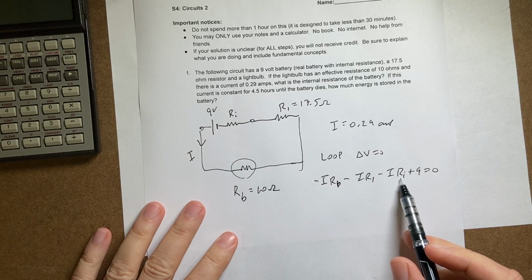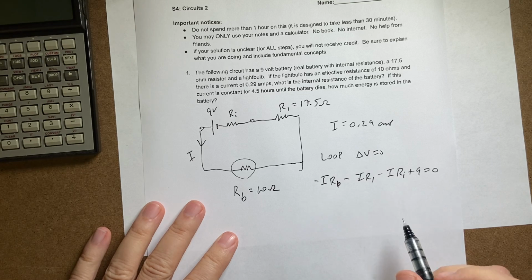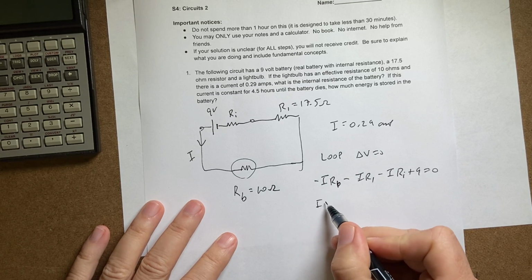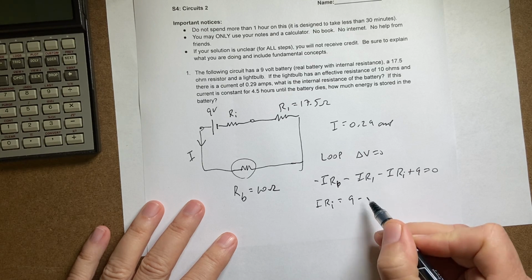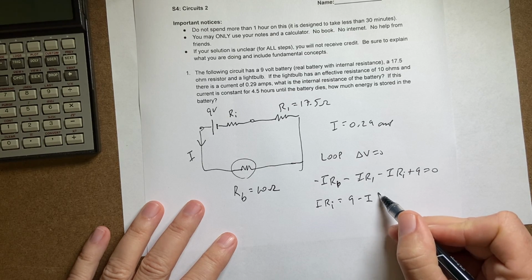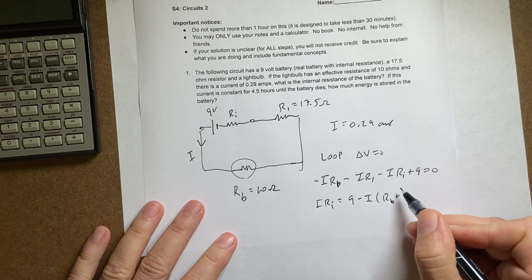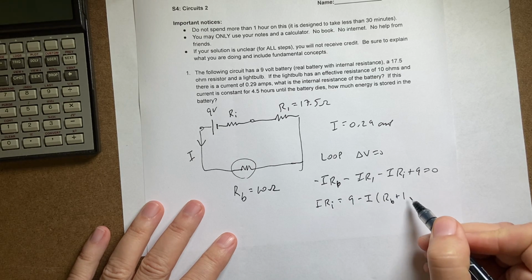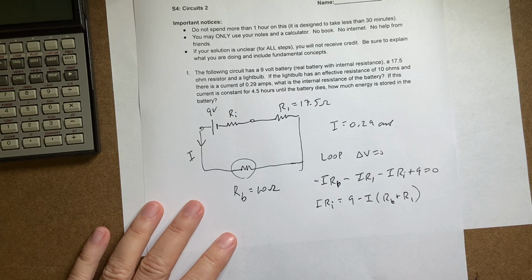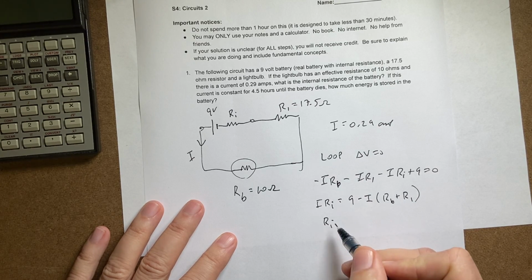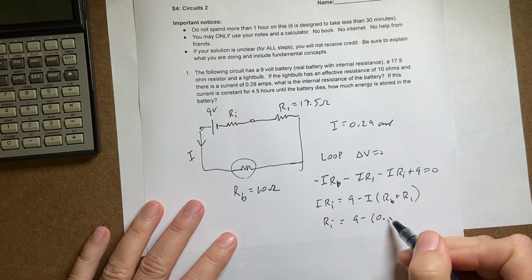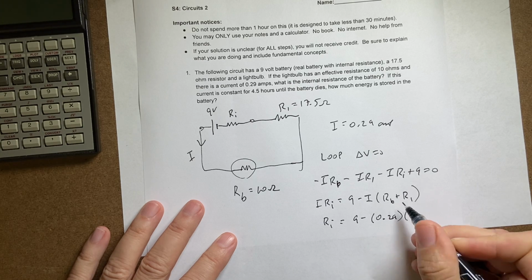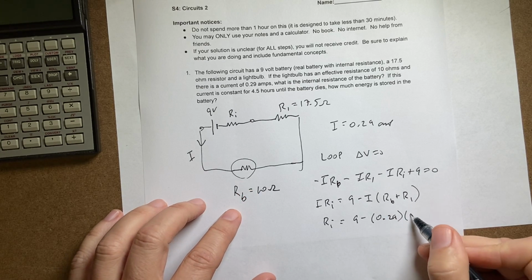So I want to solve for that. I know all these values. So if I add that to both sides, I get I R internal equals 9 minus I times (RB plus R1). That's the bulb, that's R1. So then I divide by I, and I get R internal is going to be 9 minus 0.29 times (RB plus R1), so it's going to be 27.5, I left off the units,